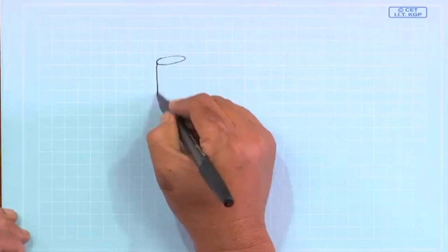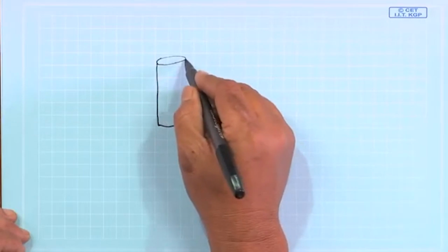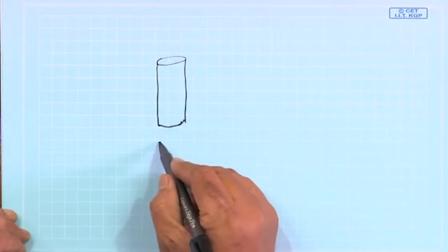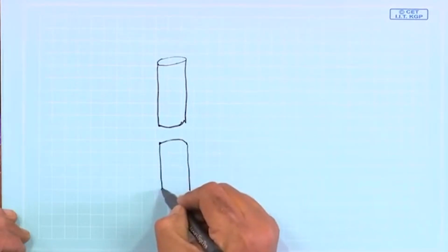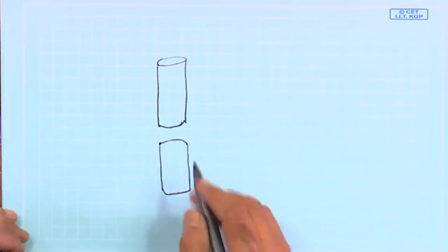Another thing is that we have a finite gap at the feed point. That gap we did not consider, because we took the dipole's center to be at a single point, but actually the dipole center is a delta up and a delta down. That was not modeled. Today we will take that also into account, so a dipole is something like this, and there is this gap.